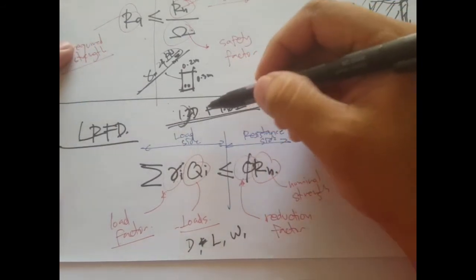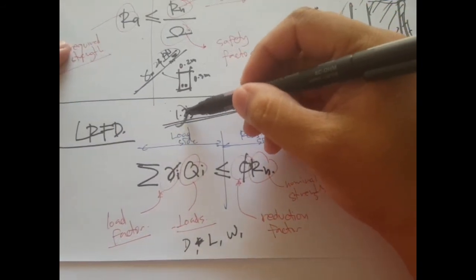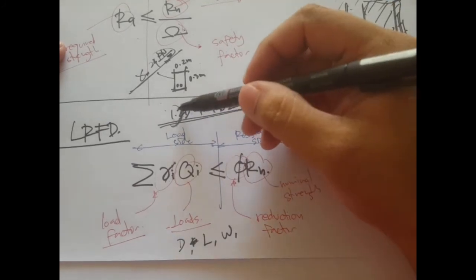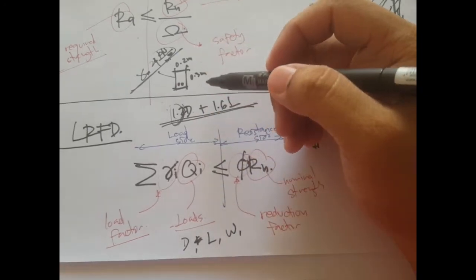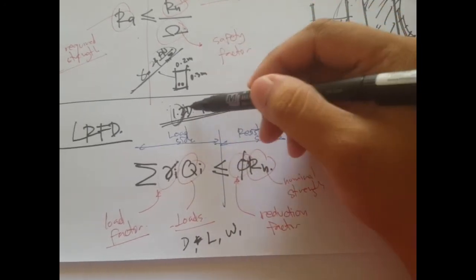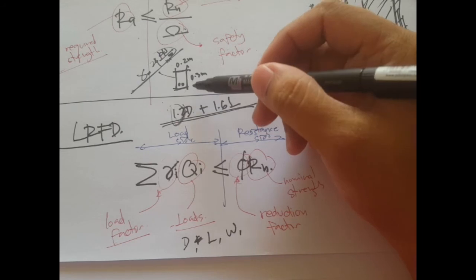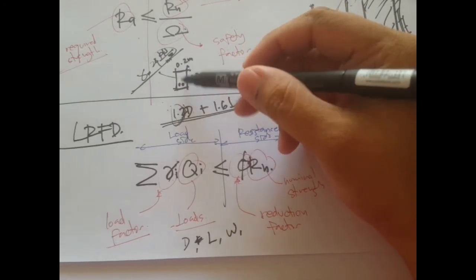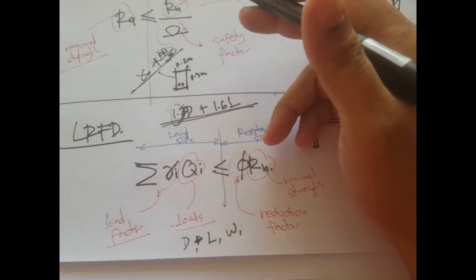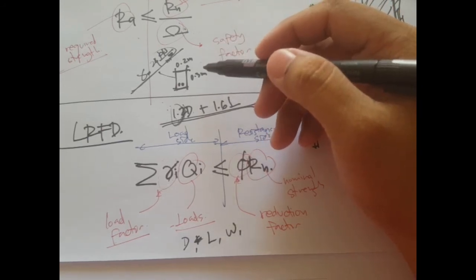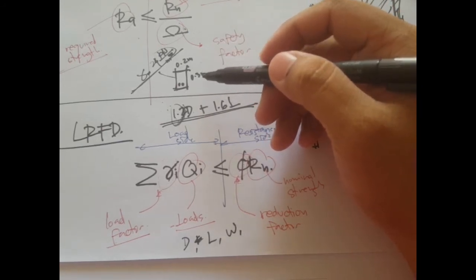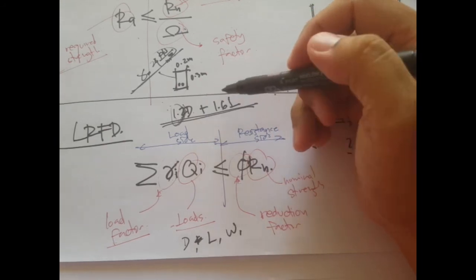But you notice that we have a smaller value than for the live load simply because we have more control, or we can know more accurately, compared to the live loads. We can determine the dead loads. If we have the dimensions, then we can determine the volume. Although there are uncertainties, we can still determine it quite accurately as compared to the live loads.